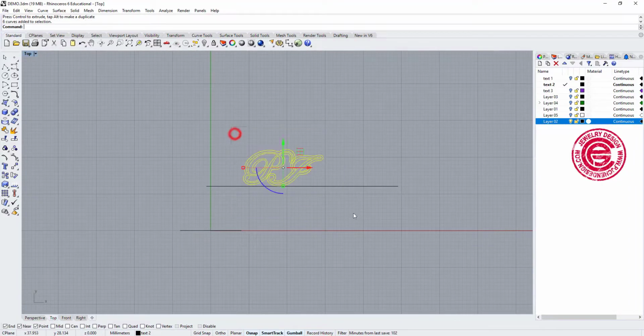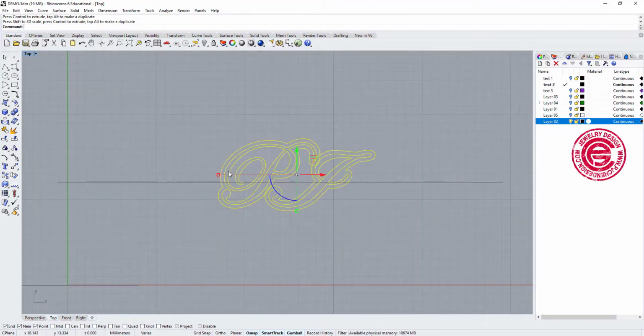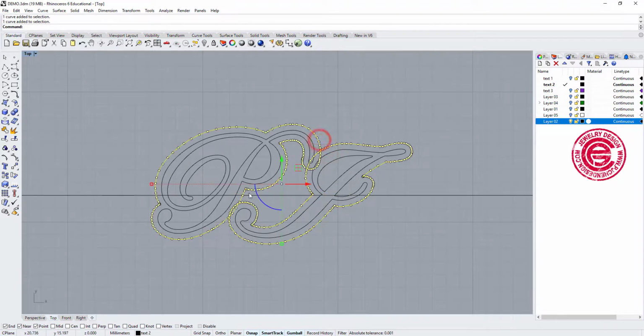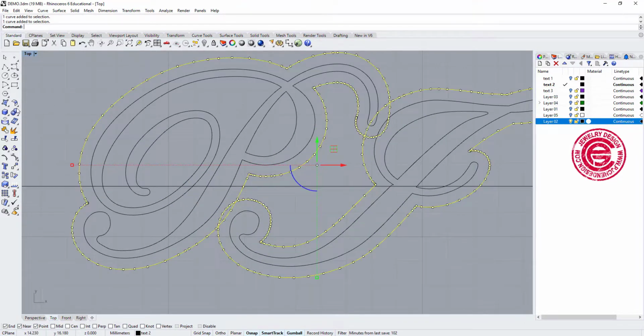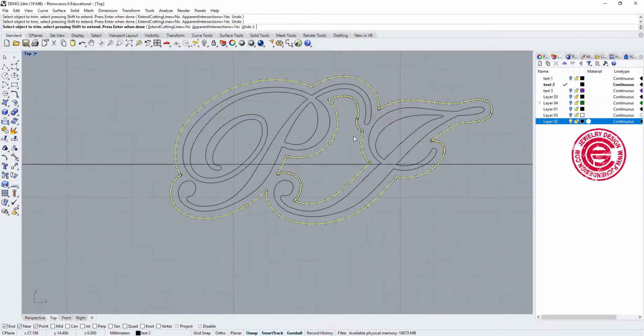At the same time, we want to compare the entire text and how much room it takes on the rest of the ring shank. That means my ring shank might be a little too short, so I'm going to scale it down just a little bit. You need to look at the proportion and see which one works best. Okay, so now we have this. I'm going to have this one and this one as our border if we really like that. Then I'm going to trim this one over here, so they will become one single line. Let's go ahead and join them.